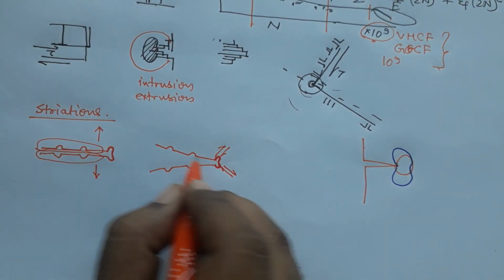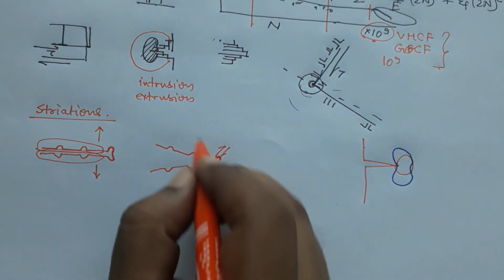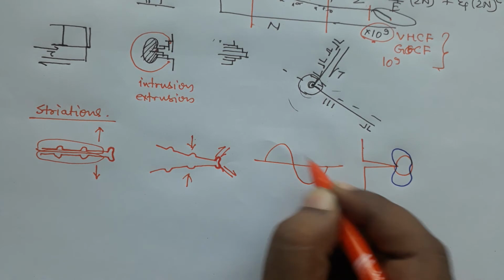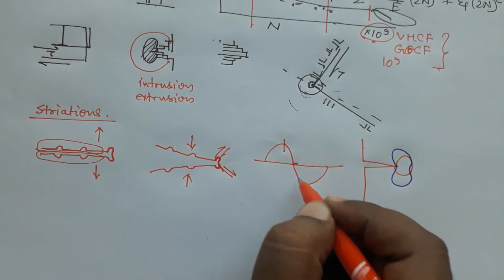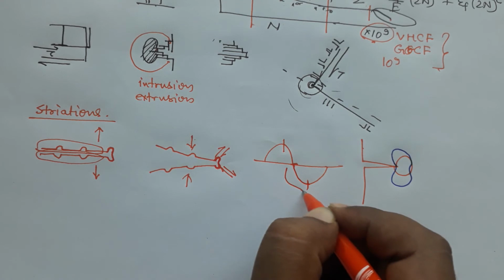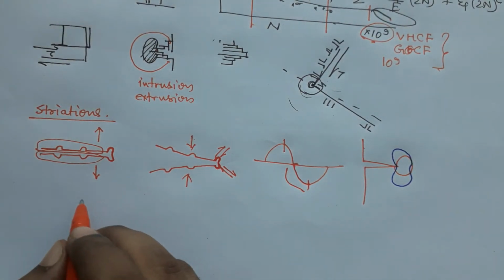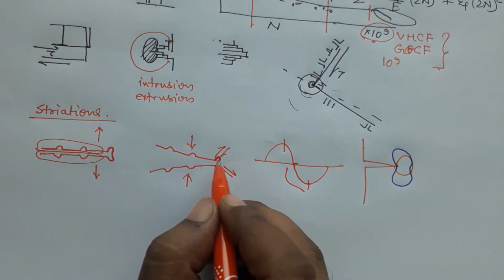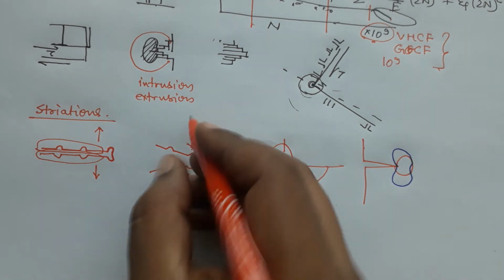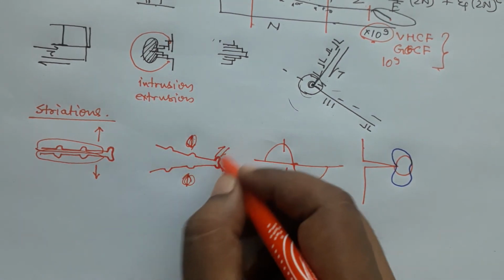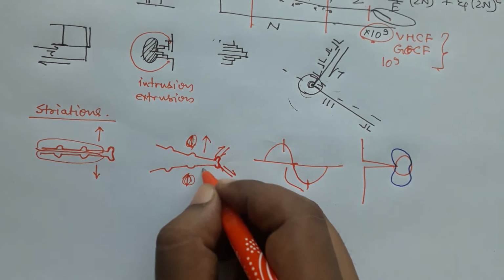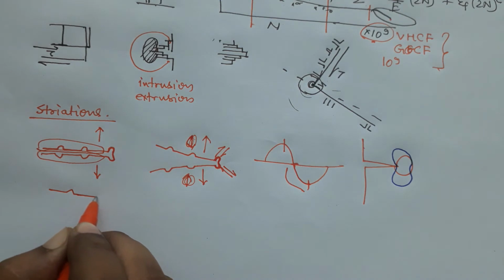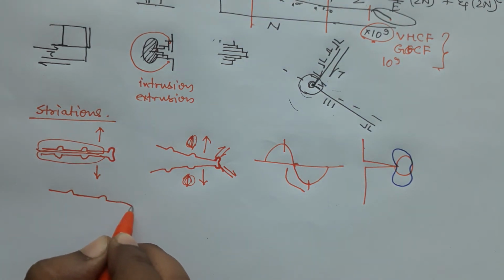So this happened in the tension part, then what you do is you apply compression. In the stress cycle you have tension till here, then you unload till here, and then you apply compression. So this is the part where you apply compression. But before compression, once shearing starts and you are still loading in tension, this crack will become blunt.